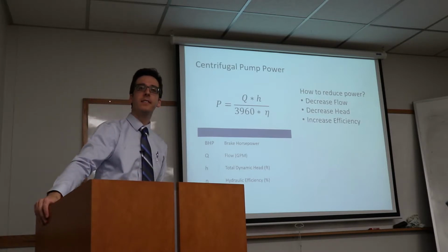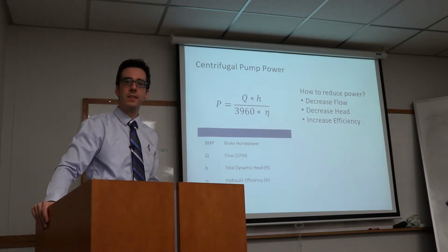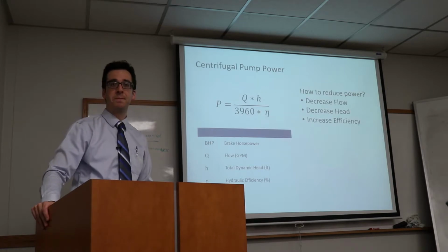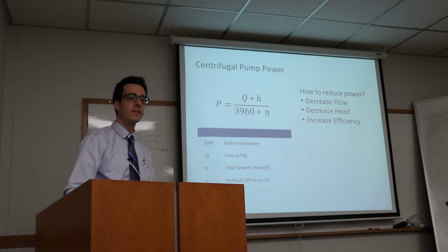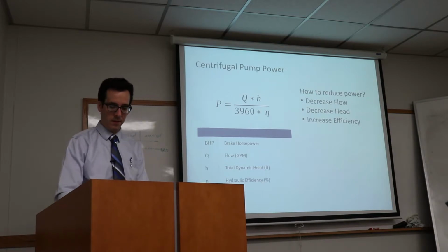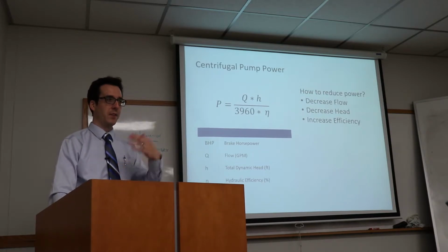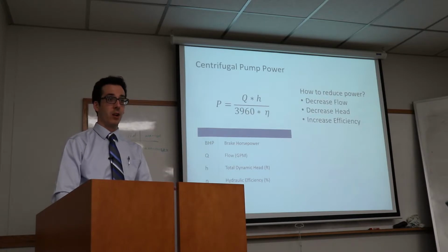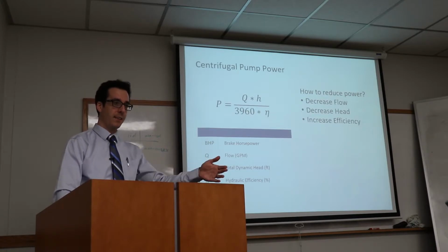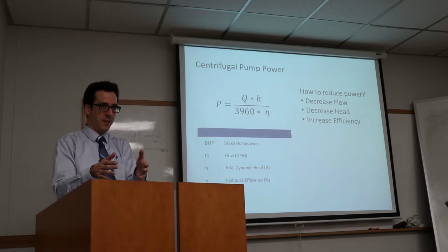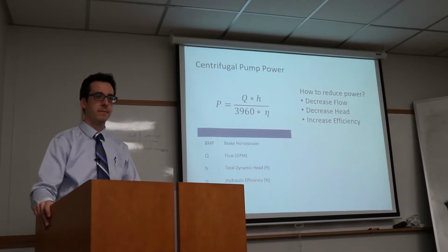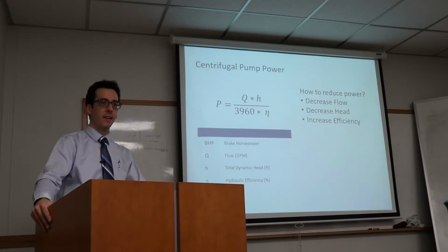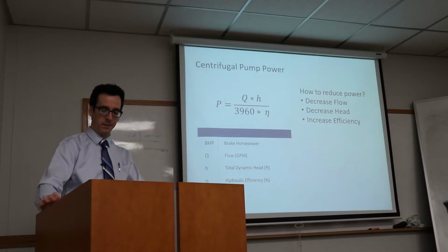Yes? When you have efficiency percent of 0 to 100, here it's a decimal, 0 to 1. Is there another question here? Yeah, what's the difference between brake horsepower and any other horsepower? So the brake horsepower is what you have to put into the motor. The pump takes some energy and then the motor has some efficiency too. So the brake horsepower is what you actually put in. So that'd be like what you see on your bill, as opposed to what you're actually getting out of the pump. Right. It's what you get charged for, if you want to think about it that way.